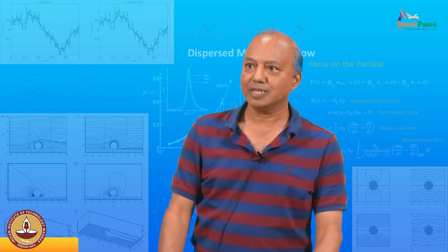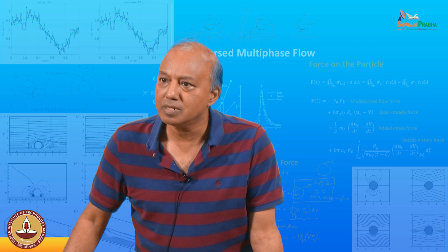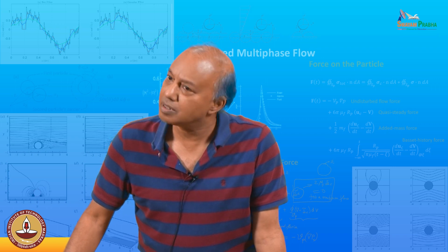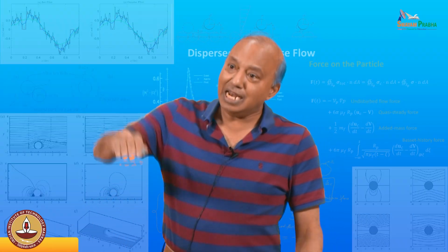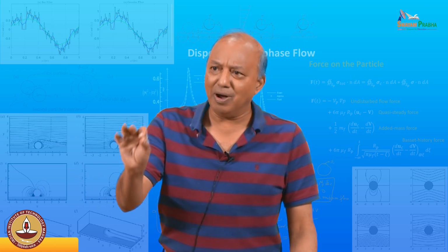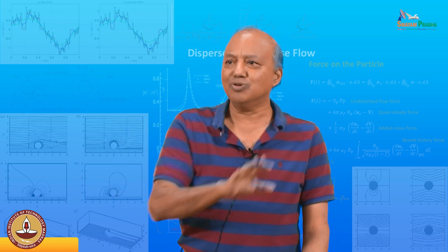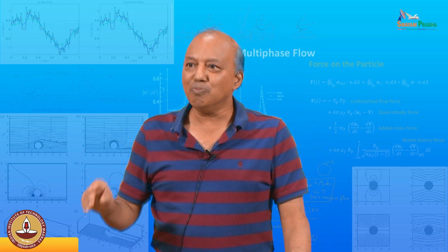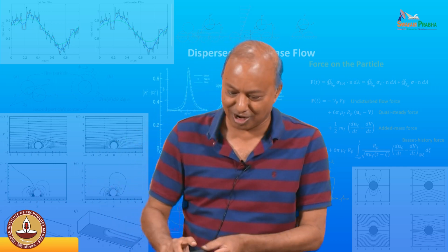For example, I have a small gas bubble, an extremely tiny gas bubble, say less than 5 mm or 3 mm in size, where the added mass has to be taken into account. Now, if it is steadily rising, this is all for acceleration. If a particle is moving at constant velocity, no problem. You must have relative acceleration. Look at this.